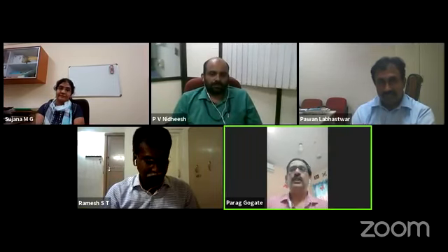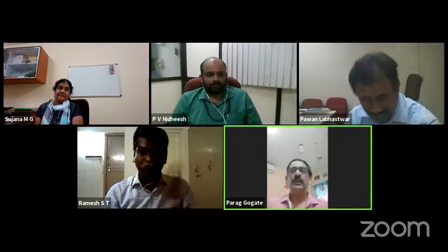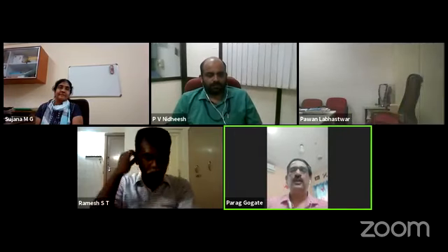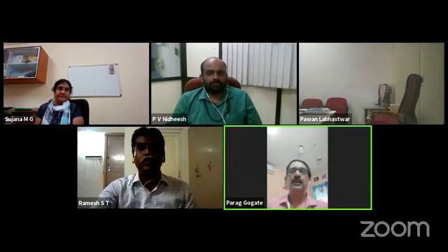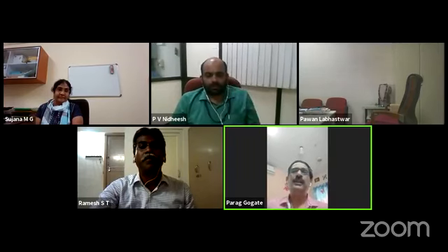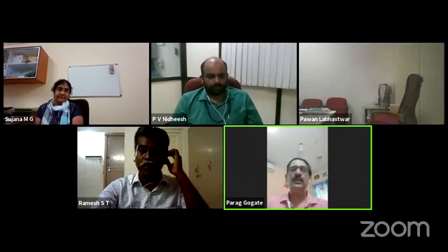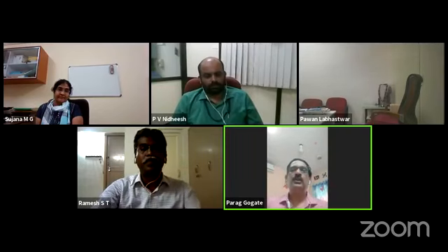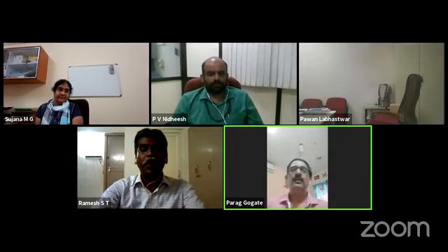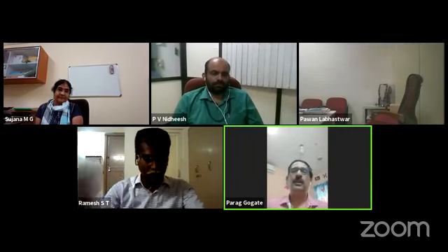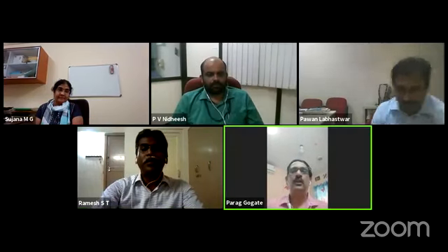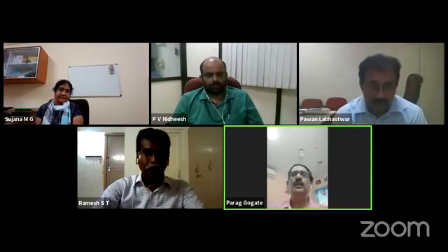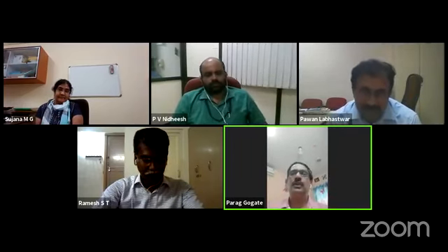Yes. So typically it will depend on the initial pollutant concentration. Of course, if you are talking about complex pollutants, then the treatment times are going to be higher. What we have seen typically, if you're using only hydrodynamic cavitation, it can range from about 30 minutes to even 2 hours. And as soon as you start combining it with oxidants, then definitely it can come down. It can be as low as even 10 minutes if you're combining it with oxidants. So that's the typical range, but again, as I said, it needs to be optimized on a case-to-case basis.